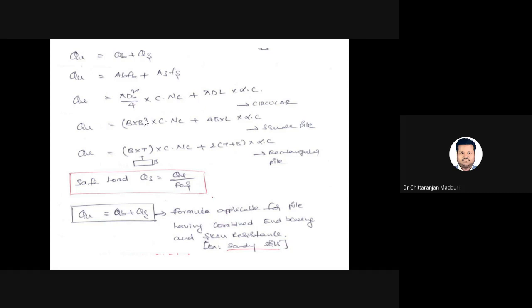So an engineer should not place the maximum load on the structure. That's why we need to take some factor of safety. So if you put 75 kgs on the pile, then it is called the safe load. The capacity of the pile is 100 kgs, but we need to put 75 kgs. That's why it is in a safe condition. The safe load is equal to ultimate load carrying capacity divided by factor of safety.